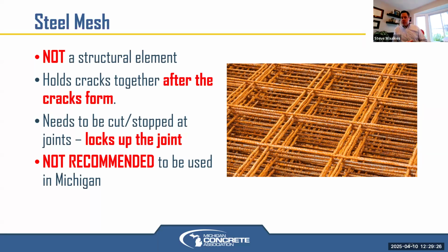And then commercial places, you'll see a lot of reference to ACI specifications, and ACI has guides on concrete parking lots and concrete pavements. So it really depends. It all depends on the facility that you're using, and the thickness of the slabs will depend on the loads using that facility. MDOT thicknesses, well, they do some 6-inch concrete overlays, but they'll go up to probably 13.5 inches, which is probably the max I've seen on MDOT highways, interstate heavy duty, like I-75 type.